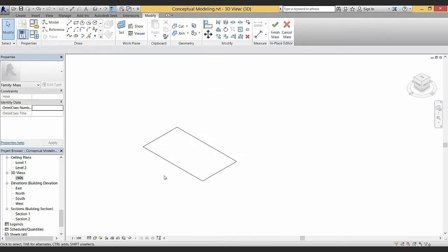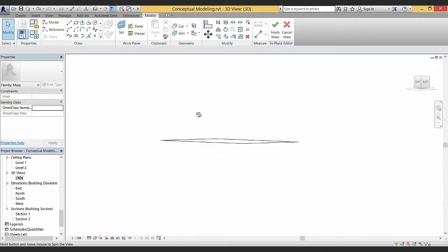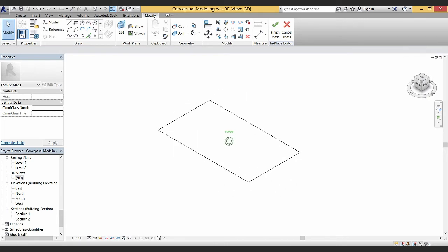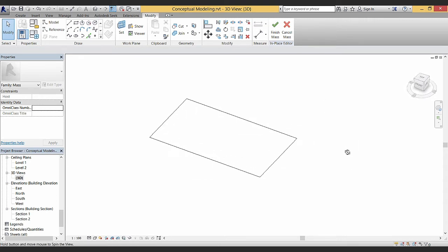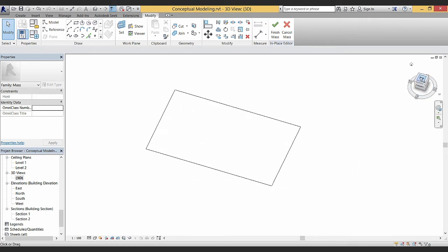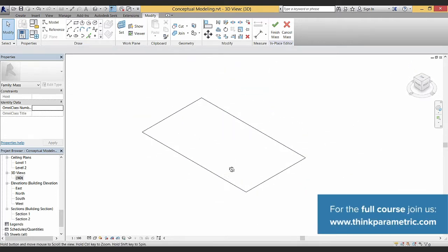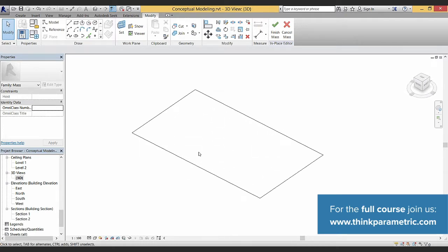Inside a 3D view, you zoom and you pan like any normal view, but in addition to that, you can hold Shift on the keyboard and then spin your 3D view like so. You can do that with the view cube by just holding your left mouse key. The view cube, in addition to just giving you the ability to orbit your 3D view, can also orient it to different sides, like the south facade or the front facade or right or top or home, like so. Getting to know these different ways of moving around in the 3D view is pretty important.